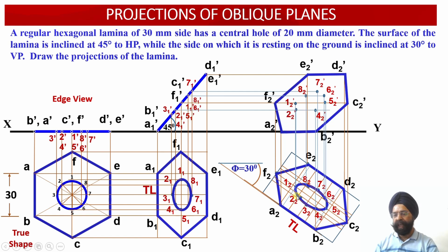From the point 2, that is 2-2 over here, we have drawn a vertical projector line moving upwards. From 2-1 dash we have drawn a horizontal projector over here, and the intersection of these two projection lines has provided us with the location of the point 2-2 dash. And here we have obtained the 3-2 dash point as an intersection of the vertical projector through the point 3-2 and the horizontal projector obtained through the point 3-1 dash. So this is the point 3-1 dash. Through 3-1 dash we have been able to obtain this horizontal projector.